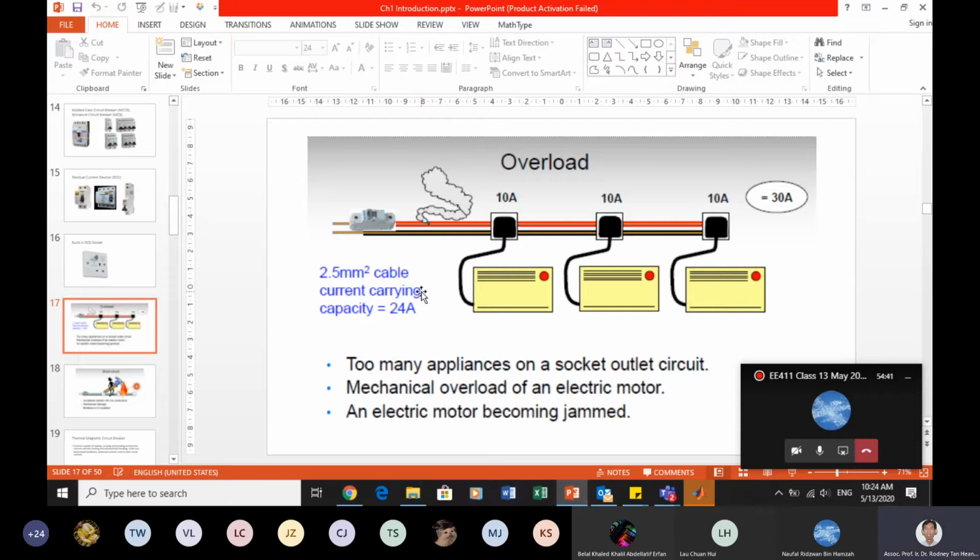Many engineers, when they first graduate, want to be electrical engineers, go to consultancy, go to contractor. Usually the very first job they ask you to do is to go to the site and do inspection. That's the basic job. Inspection is needed because the workers doing the installation, the hard job, are foreign workers who are not trained engineers. You need to go there to make sure they are wiring correctly and using the correct cable, because sometimes they cannot distinguish the different sizes of cable. Cable is cable, right? For them, as long as it conducts power. Then you have to go and touch and see, and say, oh, this is 2.5. No, this is 1.5, you are doing the wrong one. Ask them to rewire it.